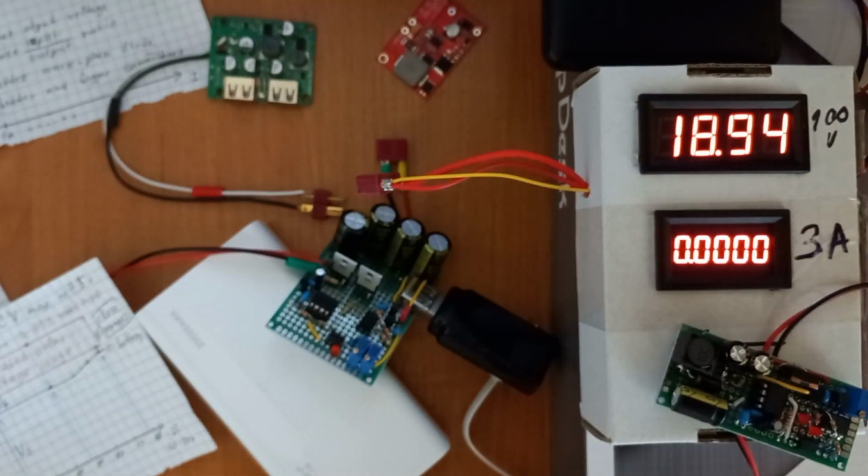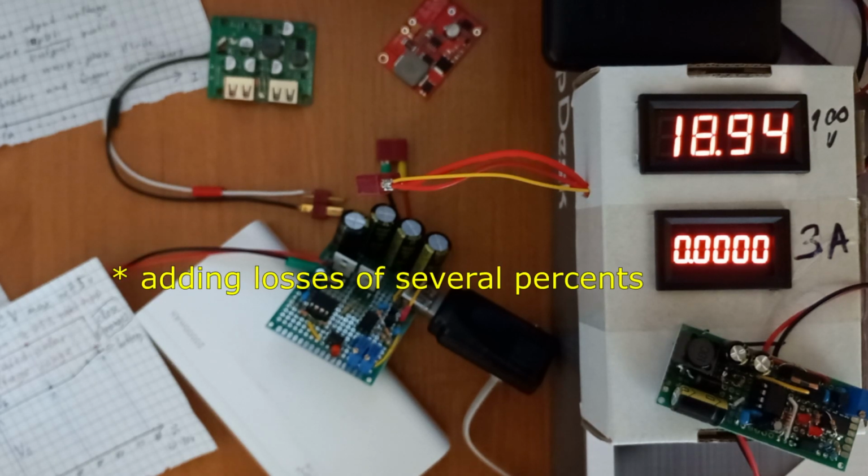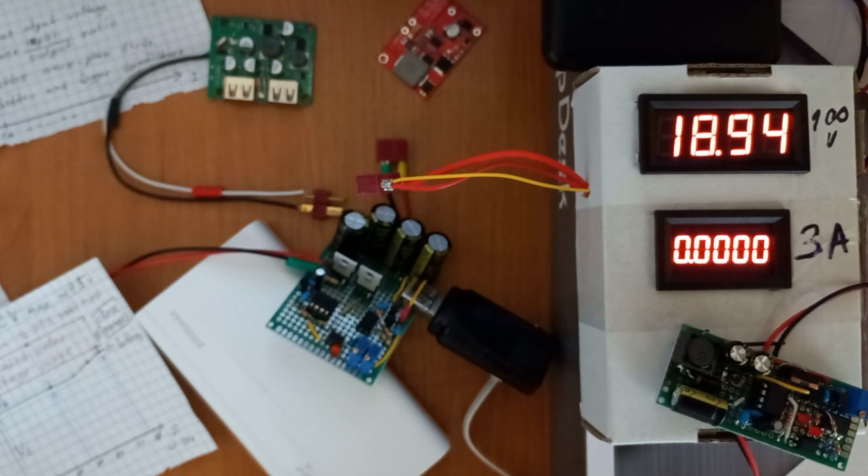If you connect solar to a battery via plain DC-DC buck converter, it will work pretty much like direct connection, but ensure that battery voltage won't exceed the specified limit. Solar PWM controllers work similarly too. They drop solar panel voltage to a level of battery voltage.